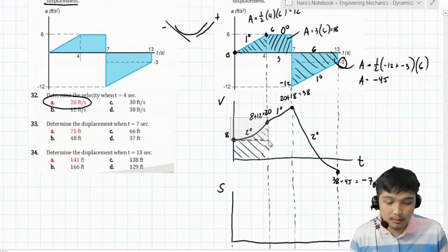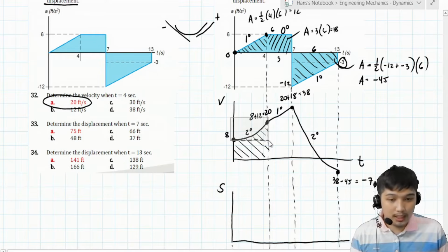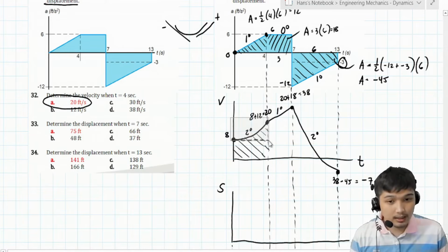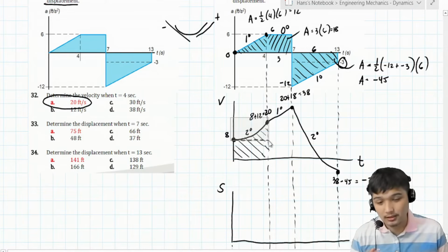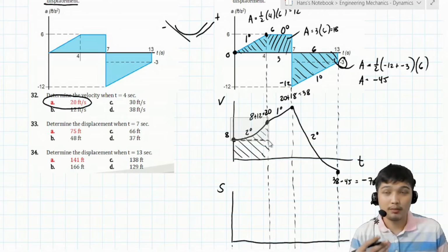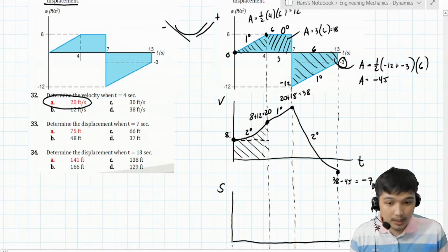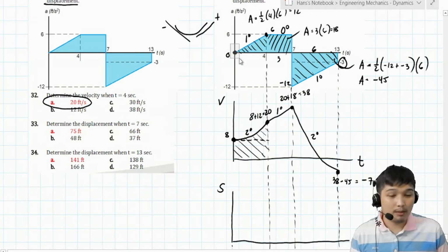So applicable ba yung formula ng spandrel? For second degree, that is 1/3 ng base times the height. So can we use that, guys? Take note, hindi siya always na ginagamit directly. May limitation yun. Anong limitation nun? Dapat yung endpoint ng spandrel must be katapat niya yung vertex ng diagram above. Okay, so ito yung spandrel na pinag-usapan.